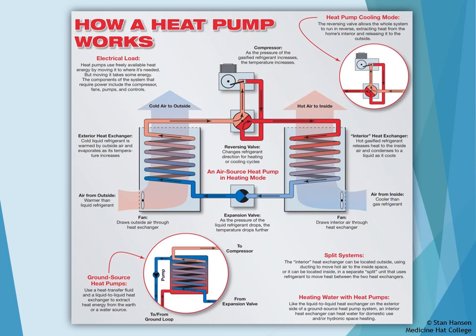The hot refrigerant will go through, transferring its heat to the inside air, and as it cools off, it will then transfer itself over to the expansion valve. The expansion valve also facilitates a change in pressure, which will cool the liquid significantly and pump the cool liquid outside. As long as the cool refrigerant is lower in temperature than the outside air, there will still be heat transfer from the outside air to the cool refrigerant.